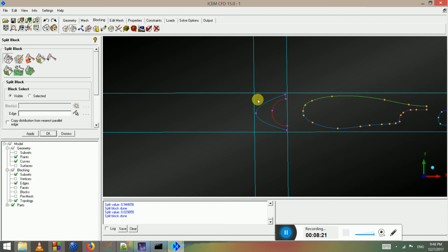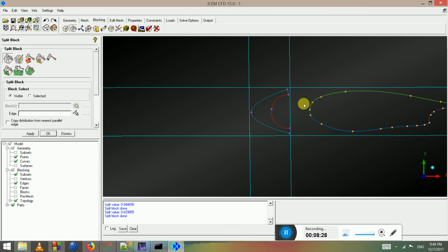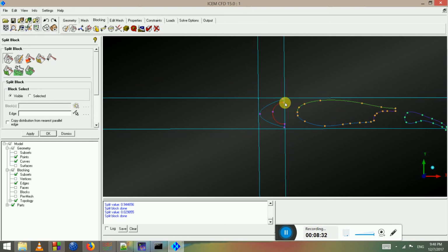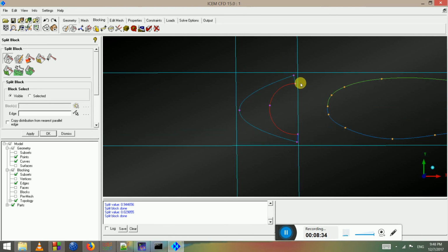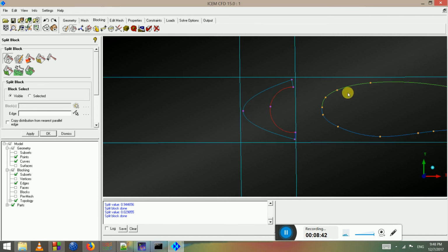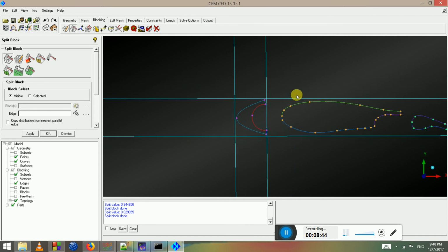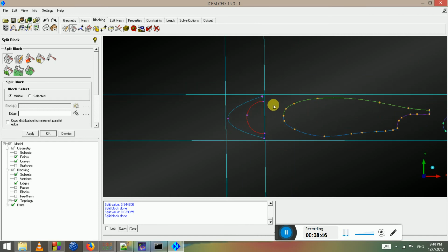So this trailing edge block, you cannot connect this edge to this wing. It needs to go above the wing. So you will get what I'm saying just in a bit. So the first thing you do is you block the slats, not the wing, the slats first. So you start from one direction. So I'm starting from the slats, and I'm going to split this edge,